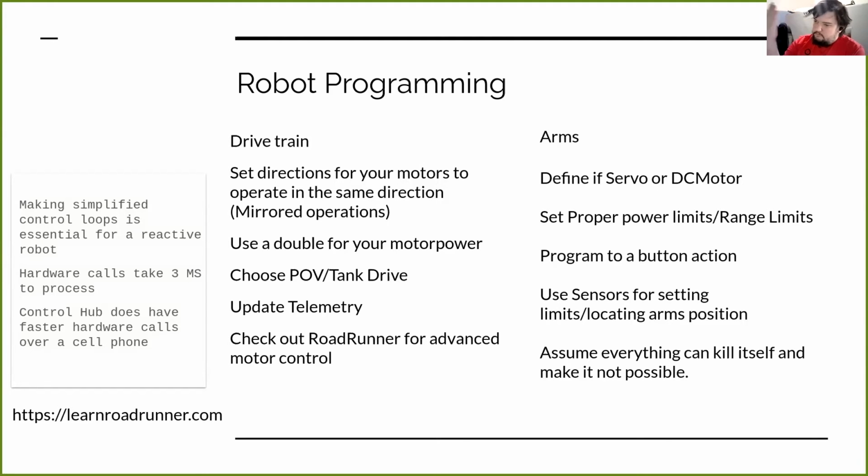So like if you have an arm with a linear slide, have it so that your robot knows what stage it's at, so that if somebody gives a command for your robot to do something that would be harmful to it, but let's say you're using a linear lift that has a gear, and so it can only go so far, and if it goes any further, you're now going to have a gear chipping against something. Okay, we'll set a limit switch so it can't go past that, or have it be encoded so it can't go a certain distance before that hardware limiter.